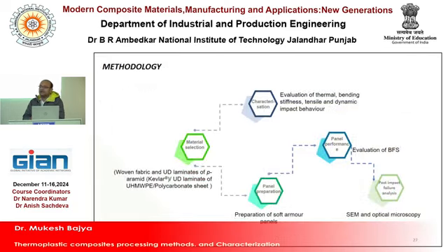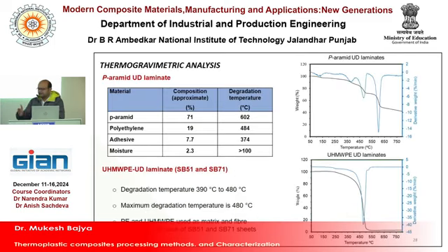We have analyzed para-aramid cross-ply laminates. Whenever you have manufactured the thermoplastic composite from aramid as well as LDPE resin, you want to confirm it: you can take a small portion of that material and see whether the percentage you decided, like 30% or 40% of the resin, actually exists, or whether theoretically calculated, it is uniformly distributed or not.